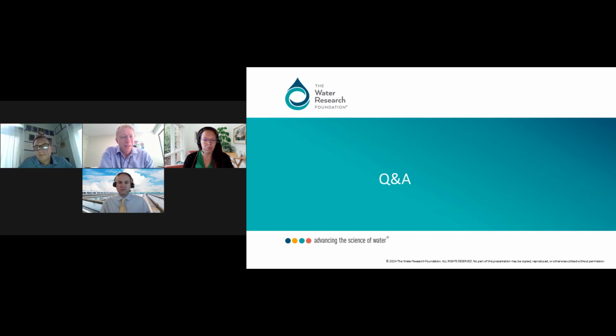Okay, thank you. We have one comment from a participant on the valves. The comment says the Brits have been using plug valves for a while for aeration control. The valve characteristics are better than butterfly valves for providing aeration control. This idea hasn't seemed to have made much headway in this country. I have one installation where I put these into service on a retrofit. So I don't know if you had any thoughts or comments on that.